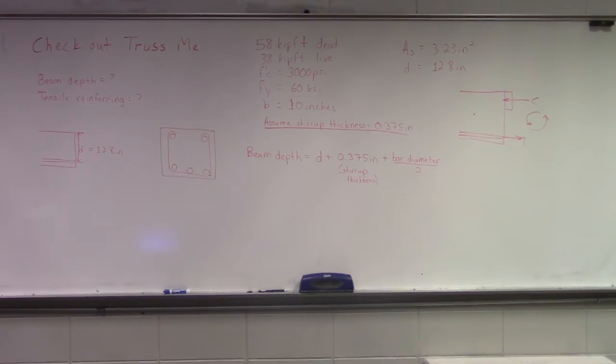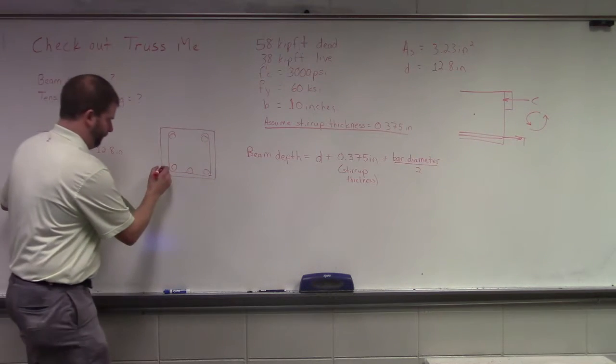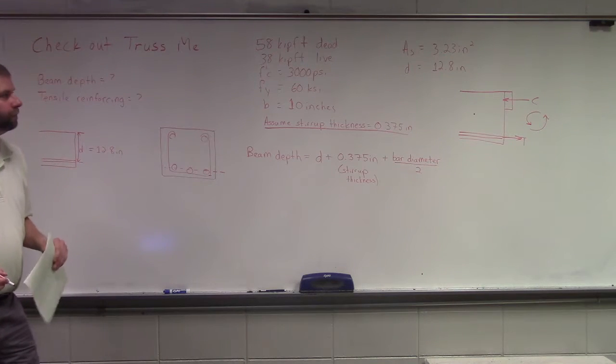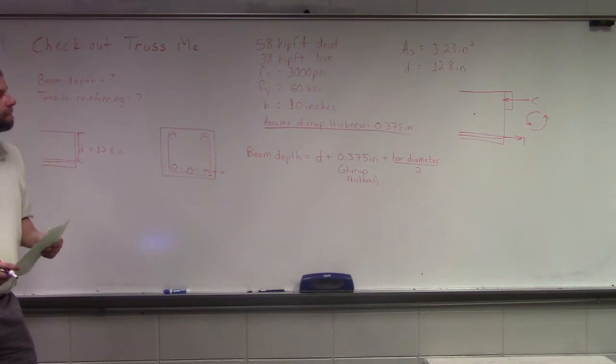Do we need to protect the steel from the environment? Aren't we just looking at one face of that? So wouldn't we take the bar diameter and try to figure out 1 bar and divide it in half? Because that's all 3. Yes, your AS is 3. So you'd want to put it down into 1 and then take half of that. So once you take AS divided by 3, divide by 2.